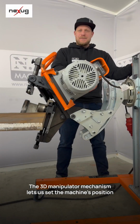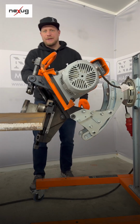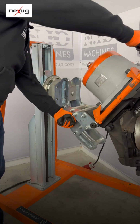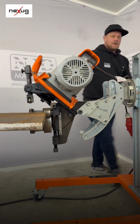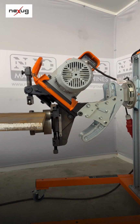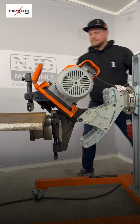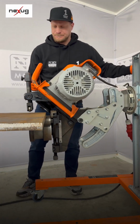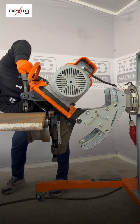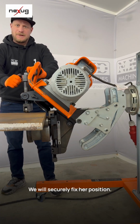The 3D manipulator mechanism lets us set the machine's position to match the workpiece's orientation while being machined. First, the machine's tilt. Following that, the height. And as the final step, we will adjust the position of the upper clamping strips now. We will securely fix their position.